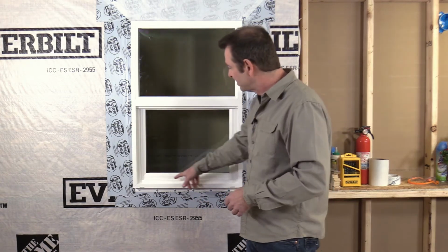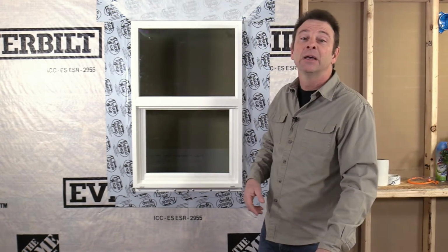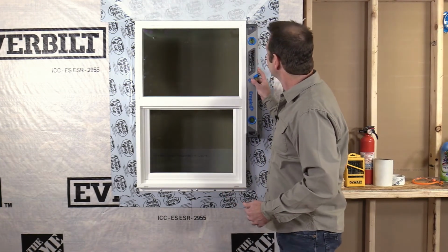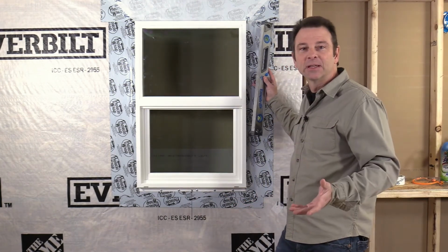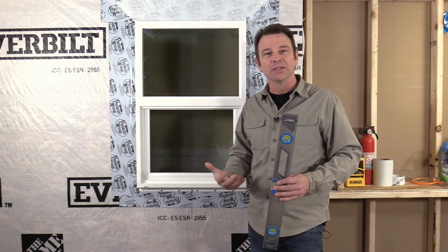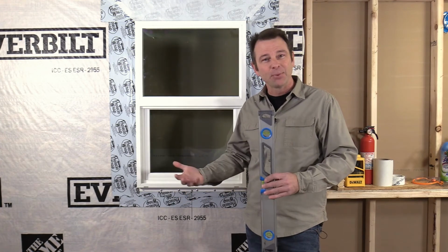If you see problems with the way the window fits in the frame, this is going to tell you that there's a problem somewhere with how that window was installed. This is a good time to pull out a level and a tape measure. Check your window for square with our diagonals like we talked about. Those should be equal. You can even use a level on the window to see if it was set level and plumb. You're the investigator. This will help you determine what the problem with this window is, if there is one, to help pinpoint where things went wrong.